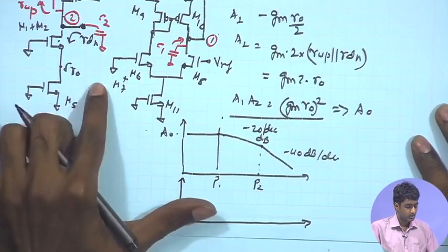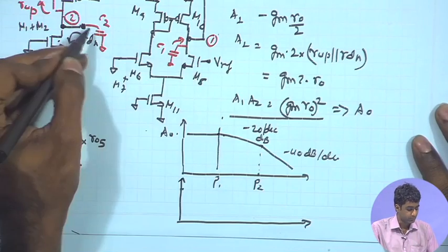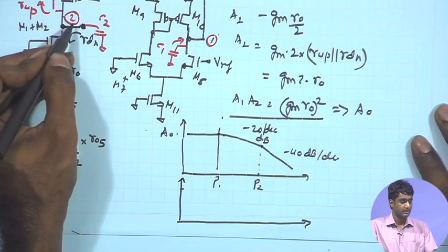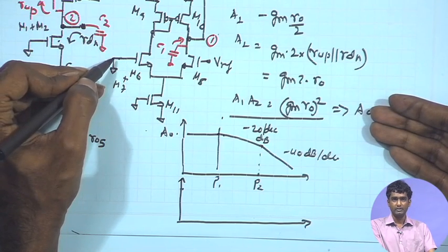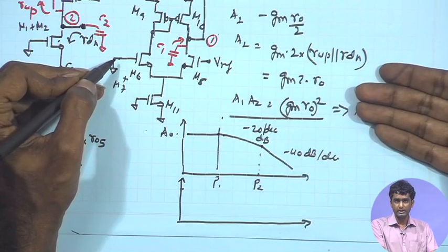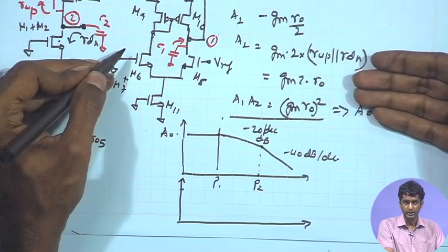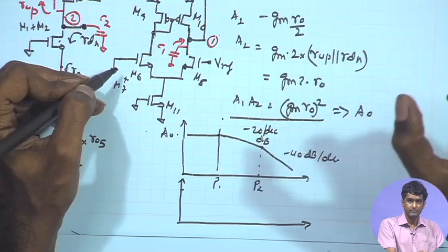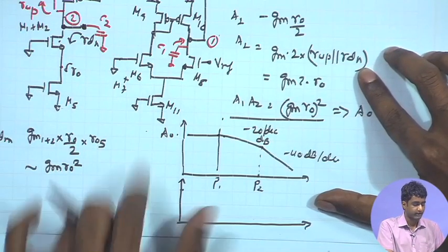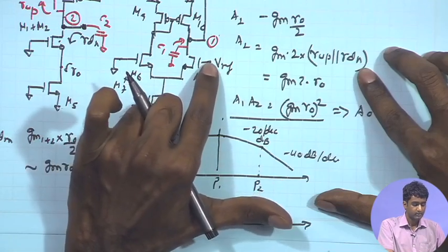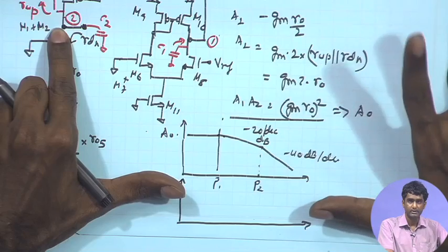So at low frequency we start with overall 0 phase. From input to the final output we have a 0 phase. Remember, there is a minus 1 term in the loop coming because the final output signal is applied at the inverting terminal. So that automatically gives a minus 1 factor and hence 180 degree phase shift across the loop. So effectively, the 180 degree phase shift is already available, and we are keeping that as a constant factor. Apart from that, if you look at the signal phase from input to output, starting from the very low frequency, ideally it should be at 0.